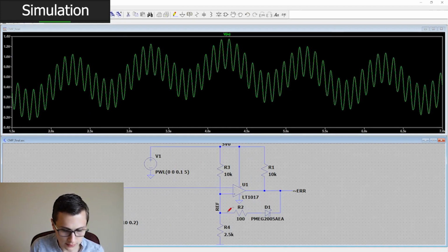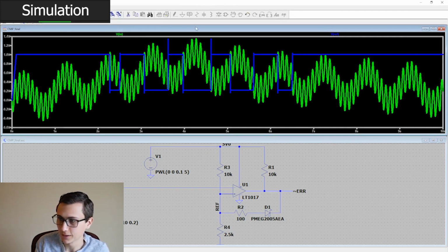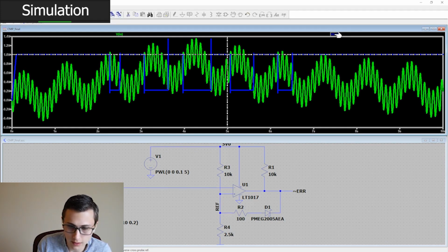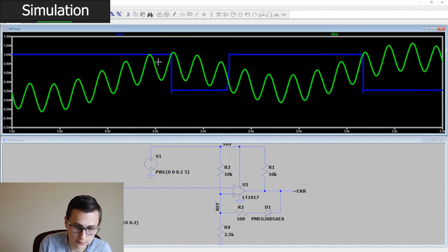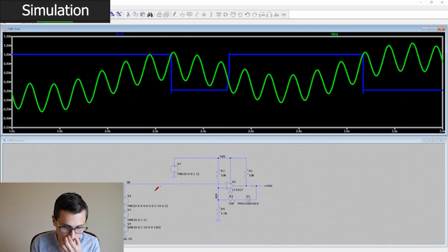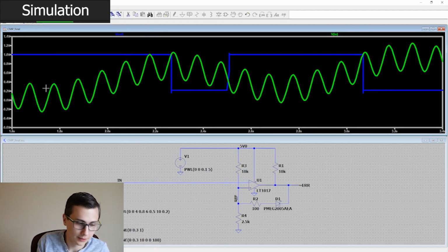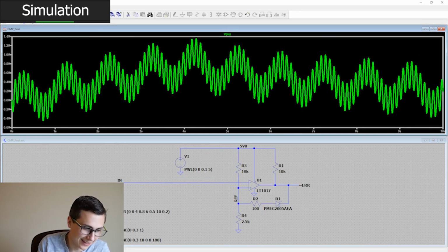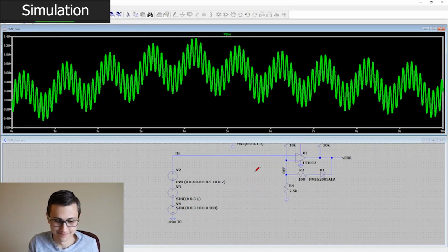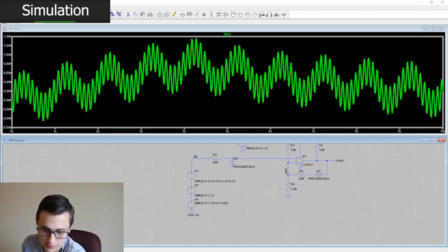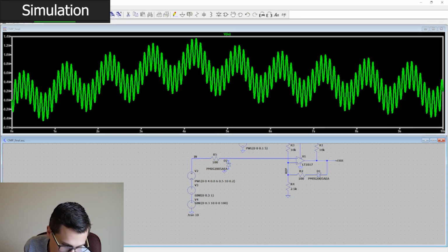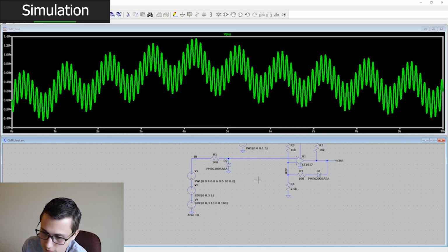And why is that? Well, let's take a look at our reference input. Hopefully that's a little easier to see. I just made the waveforms a little thicker. So if we look at this reference and we look at our input, you can see there is a great deal of hysteresis, but not quite enough to keep us latched forever. In fact, we actually go negative, which means, okay, ignore that negative voltage we're applying. I don't like that at all. Perhaps what somebody should do is grab a diode and clamp that to ground so that we don't do that anymore, so that things work.